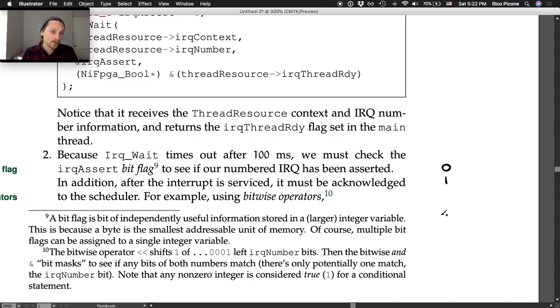So what we'll often do, if you've got embedded situations where you've got a limited amount of memory, is use bit flags. In my byte, let's say this is a nibble, and then another nibble. So there's our byte. We'll use all 8 of these bits for different flags. They're not necessarily related to each other, but they might represent, say, an 8 pin bank of a connector, which would be a good way to go with it.